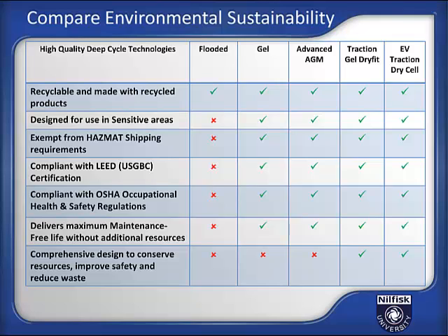The reason that flooded would not be compliant with LEED is that it's not a maintenance-free product, but it also has definite health and safety issues to consider when managing that product. Compliant with Occupational Safety and Health Administration regulations only applies to gel, advanced AGM, traction gel Dryfit, and EV traction dry cell because of their sealed and maintenance-free nature, and delivers maximum maintenance-free life without additional resources.